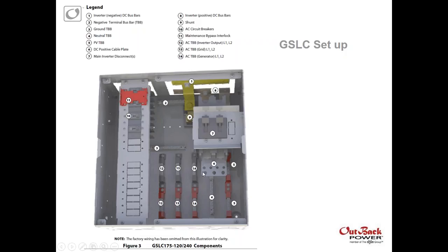Now, with the SolarEdge system, you don't need all that extra wiring. It's actually a pretty simple standard box, and you're strictly using that relay to tell it to turn off, and so you don't need any of the motorized circuit breakers and those types of things. Additionally, you save a couple hundred dollars by getting this load center rather than the pre-wired one.